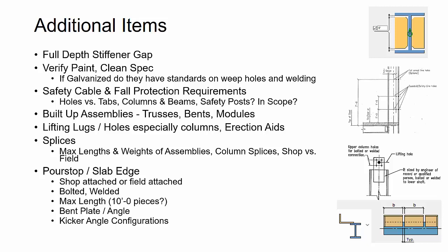And then also from a welding point of view, of welding that and doing the stagger weld along the length of that, they like those shorter pieces that they can control and prevent deformity on. Now, some fabricators don't like to weld that bent plate. They actually like to bolt it. So you have to ask that, and if it is bolted, what are the edge distances and the slot requirement that's needed for tolerance to do those?